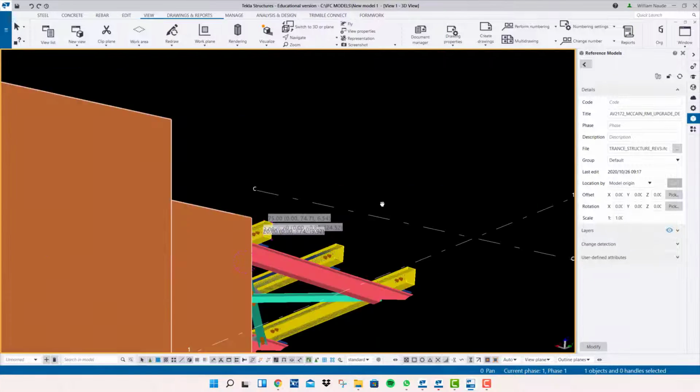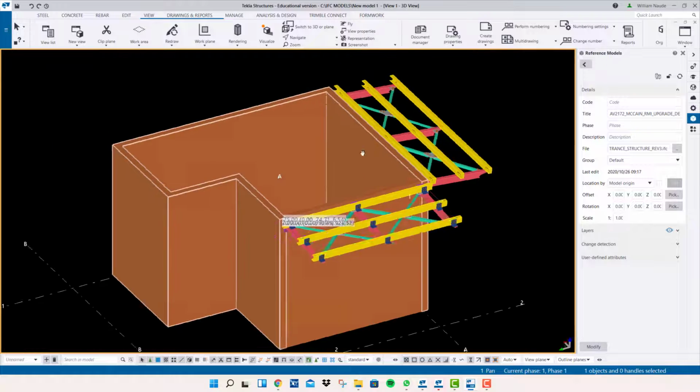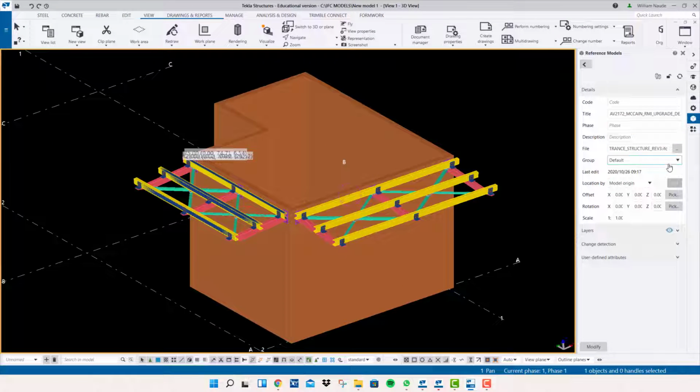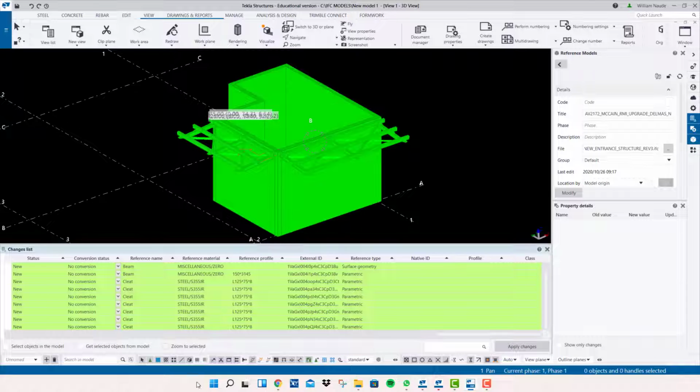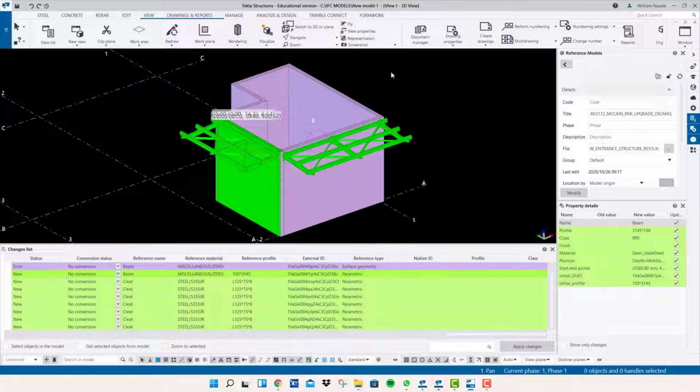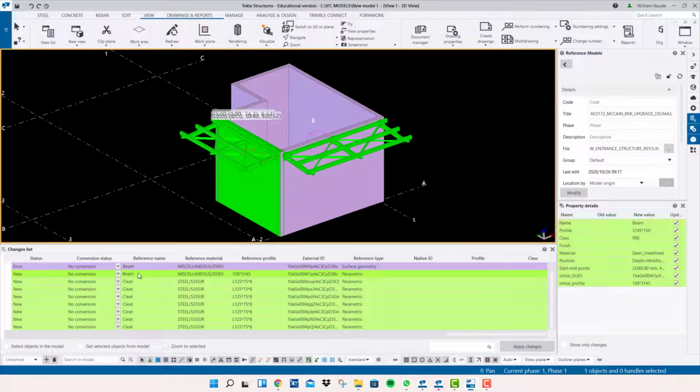Now, the other function that Tekla brought into this is the conversion of an IFC file part. So let's do that just quickly. You're going to go to your Start, IFC Object Conversion, Change Management. Once you've chosen this, a new toolbar comes up. So now, if you select one, it will highlight what item this is. Now we don't want to, for instance, convert the beams or the items marked 0, right?